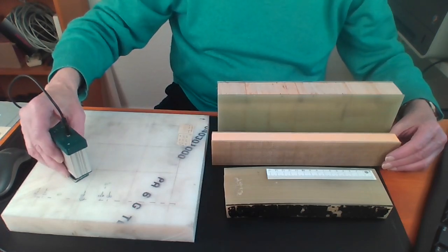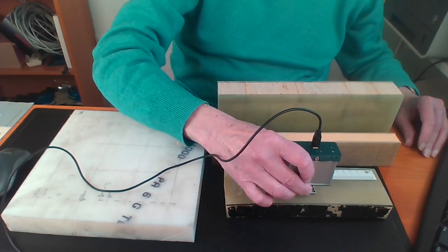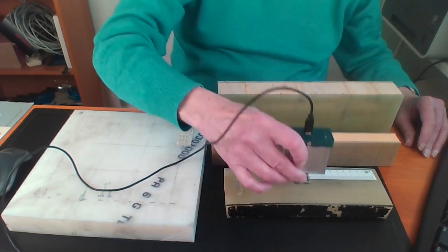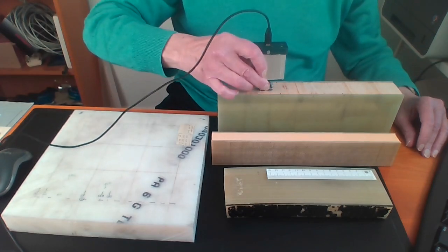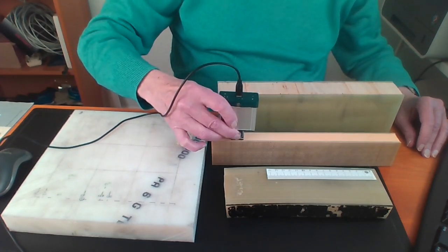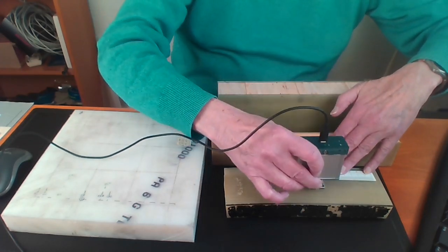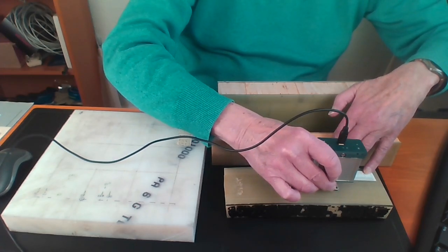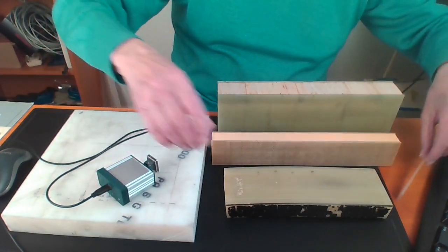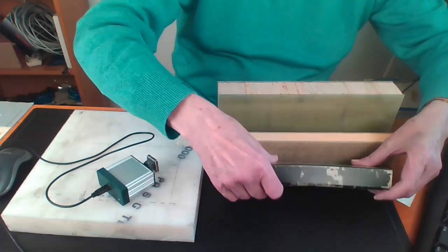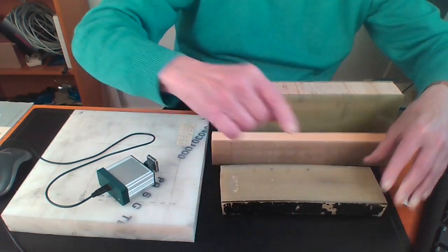We will place the test head on the surface of these materials, GRP, polyamide, balsa wood, then the plastic foam, and we will then do the scan here again to see the signature of the hidden defect, which we had also seen before, the defect which cannot be seen from the top.